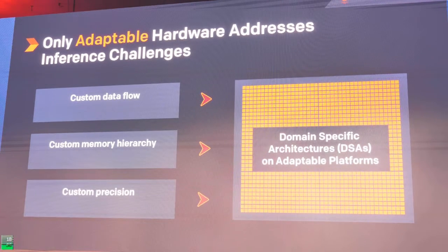Now, Xilinx and others have created something called domain-specific architectures. Victor talked about it. DSAs, domain-specific architectures. These can be created and tuned for a class of networks, a class of the current state-of-the-art networks. And these optimize across these vectors: custom data flow, custom memory hierarchy, and custom precision. You can customize all of this to improve your latency, your power, your cost, your efficiency.